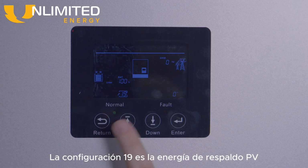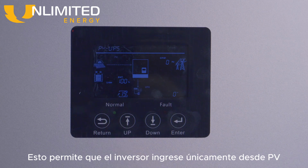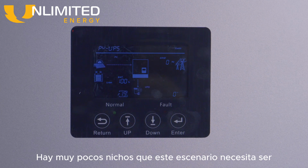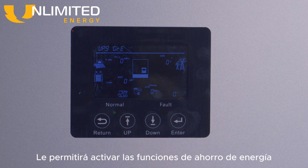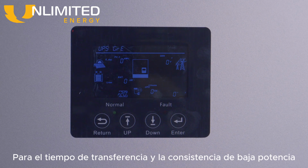Setting 19 is the PV backup power. This allows the inverter to input solely from PV. Due to the fluctuating nature of PV input power though, there's very few niches that this setting needs to be active for. Setting 20, Power Save, will allow you to activate the power saving functions, which will trade idle wattage consumption for transfer time and low power consistency.